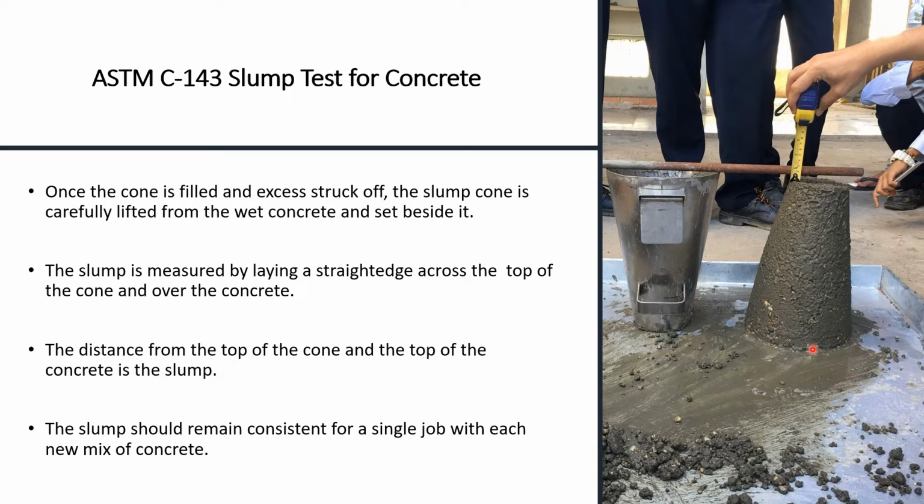The slump should remain consistent for a single job with each new mix of concrete. Otherwise, the concrete you are adding to the building wouldn't be consistent. So if you want a consistent strength for your building, you definitely need to do this slump test every time you mix.